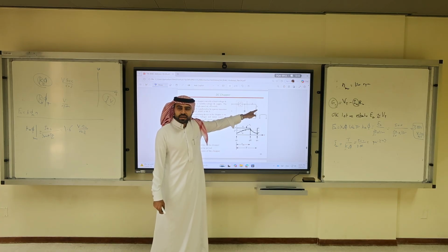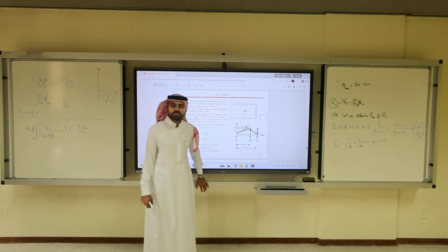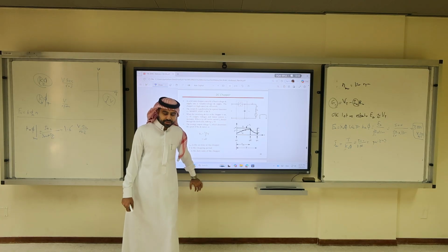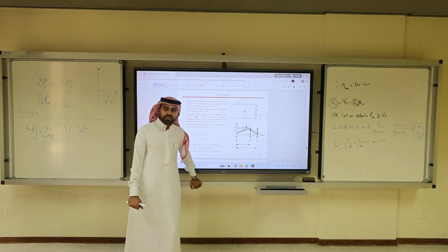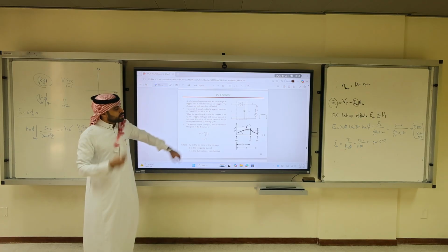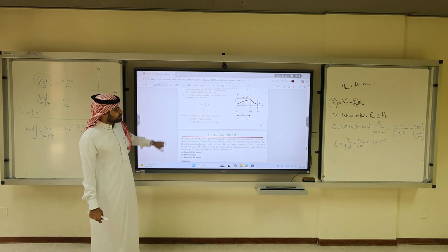Nawaf, why do we have the inductor? Why do we have LA? So it doesn't change suddenly, and we capture it in dynamic, not steady state. Do you use equations or Simulink? Simulink. Okay. So that's the duty cycle, and that's how IA works.